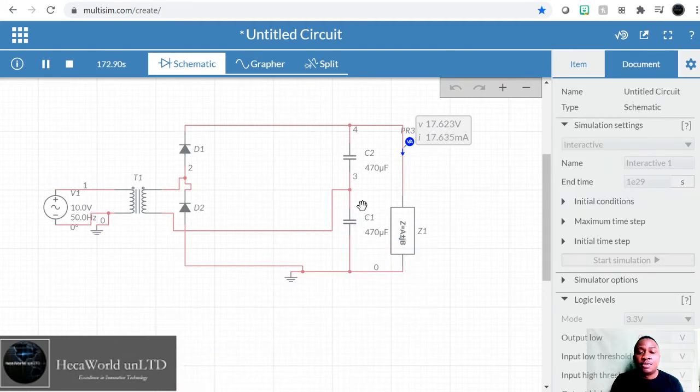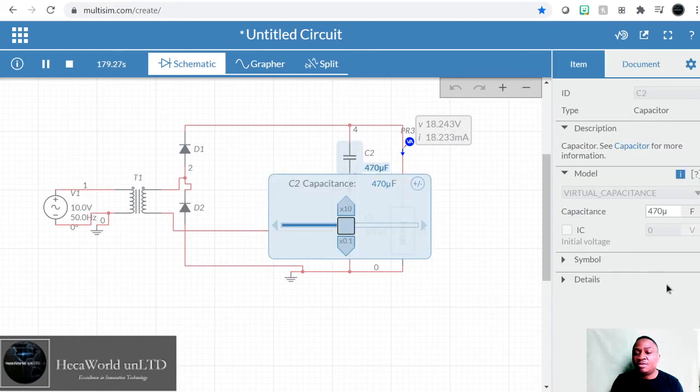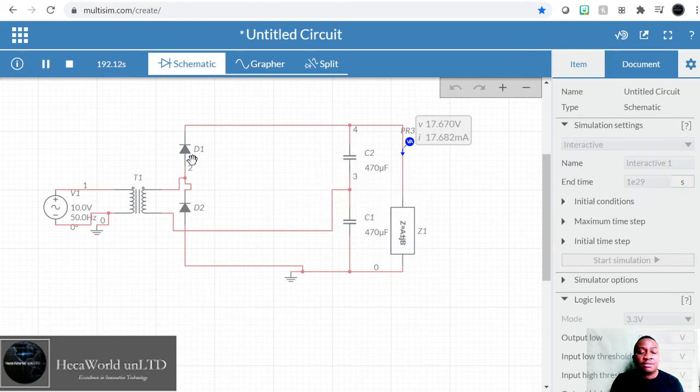Of course, make sure that the voltage rating is at least 1.33 times the value of the input voltage. So this is what you're seeing right here. When I say input voltage, I mean the voltage on the secondary side, right? Not necessarily the primary side. So we have shown this now. You can go ahead and do this if you want. You can build out this circuit and see how it functions.